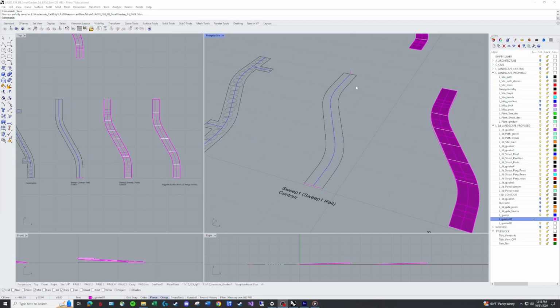So now I want to look at an example where we actually have the path slope to this straight section, and then it maintains a gentle slope along the straight section, and then it continues to slope upward to the 18 inches. So a lot of times you'll have a path that changes slopes along the way.